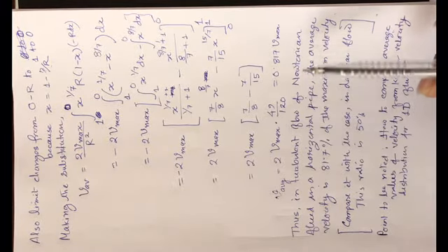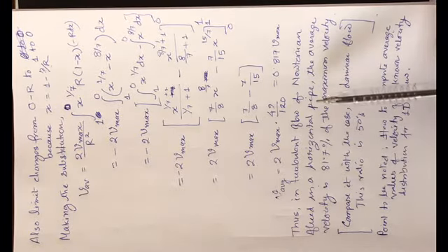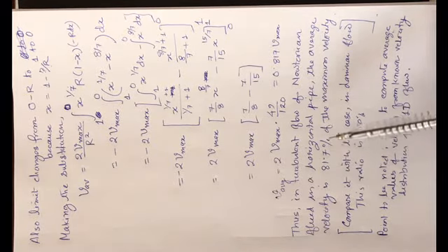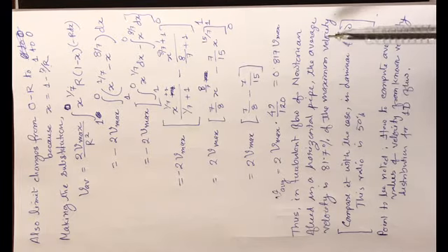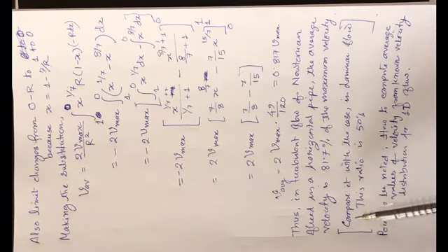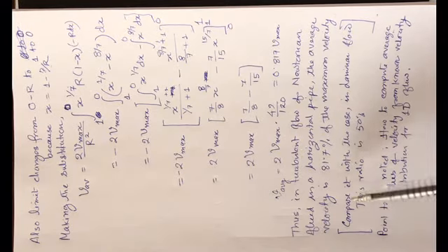This gives us the relationship between average velocity and maximum velocity for turbulent flow of Newtonian fluid in a horizontal pipe. It means this average velocity is 81.7% of the maximum velocity. Maximum velocity happens at the center. Now, to understand it better, you can make a comparison with whatever we had done earlier.